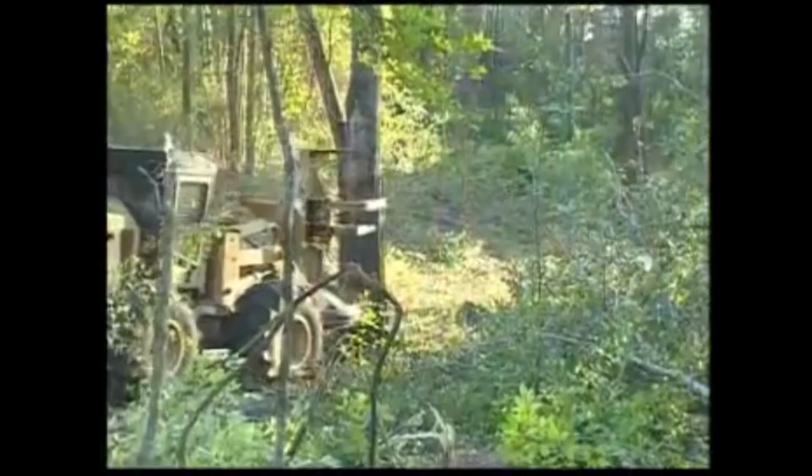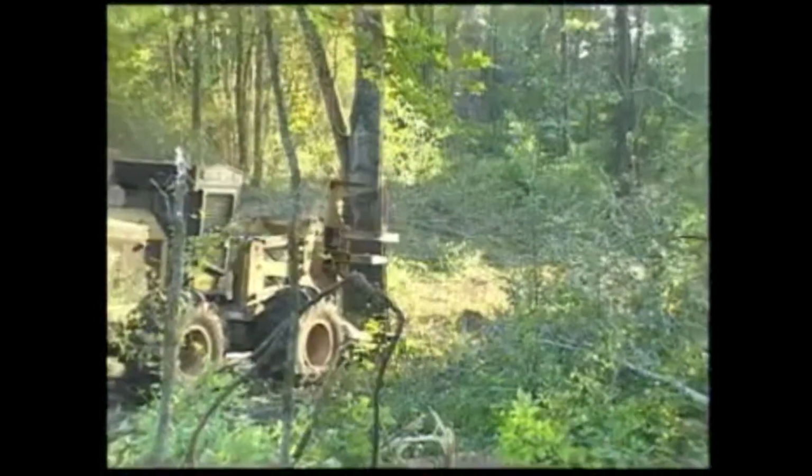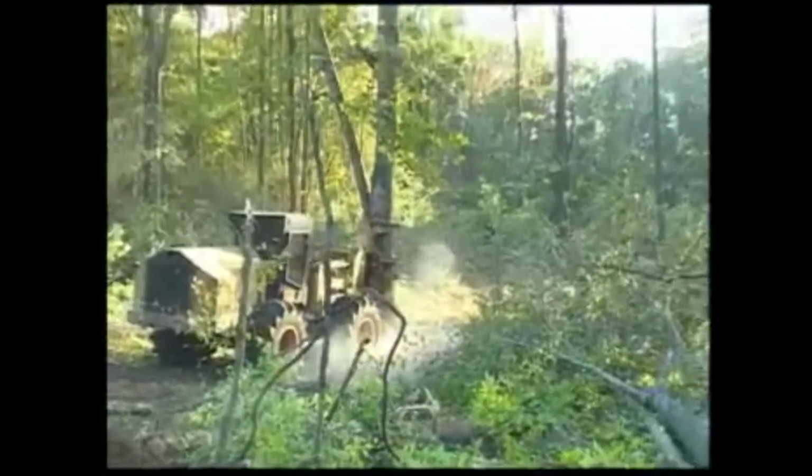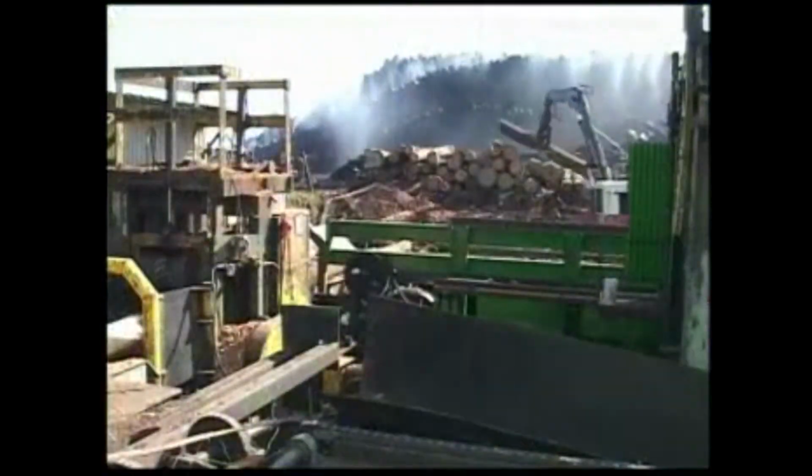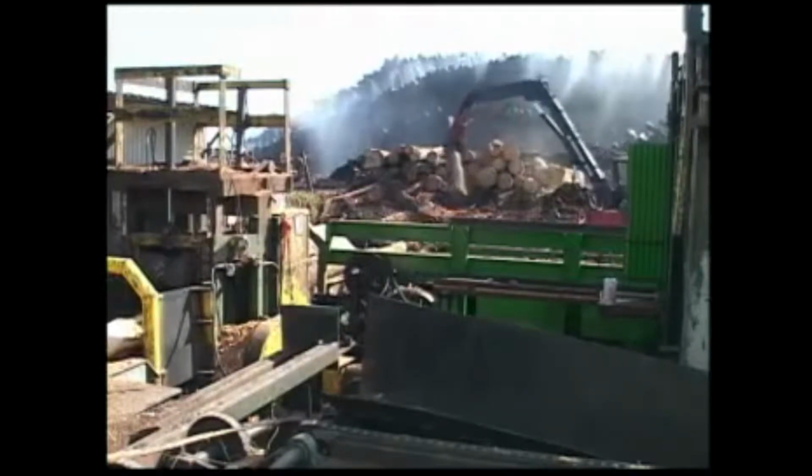Let's take a look at the characteristics of wood and how it affects the making of hardwood flooring. The average tree contains at least 89% moisture, which is reduced to an ideal 7 to 8% moisture content before allowing it to be processed into a dimensionally stable product. This process requires a minimum of 5 to 6 months.